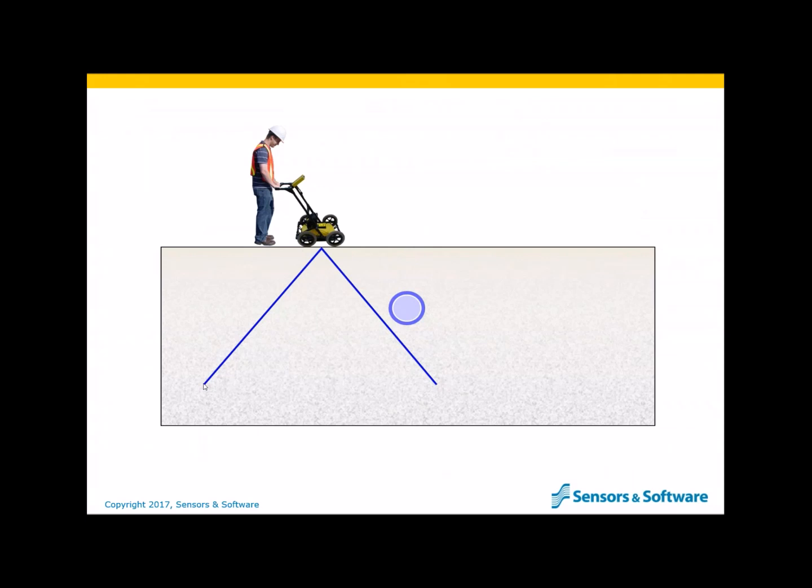Let's talk about the effect of the shape of a target. Before we discuss shape, I just want to remind you of something we discussed in part 1 of this webinar. Remember that GPR energy does not just travel straight down like a laser beam. It radiates in a cone under the GPR system. This means that as you move a GPR system along the surface, there's GPR energy traveling ahead of you and behind you that can reflect from subsurface objects.